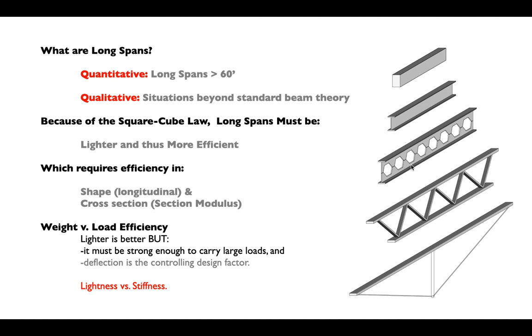If we want to push this even further, when we talked briefly about trusses, we talked about the fact that a truss is basically two flanges, right? A tension flange on the bottom, if it's simply supported, compression flange on the top. And then instead of the web of an I-beam, a truss just basically has this network of triangular panels, chords that form triangular shapes. And what those chords are doing is making the two flanges work in tandem. They're taking the place of the relatively heavy web.